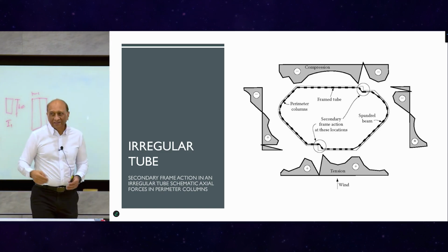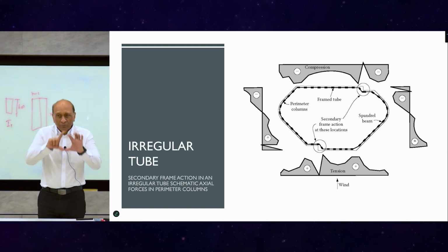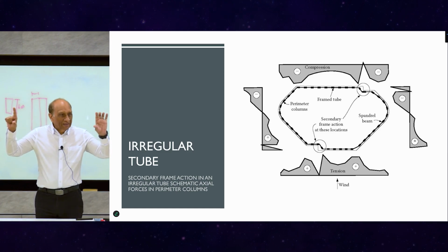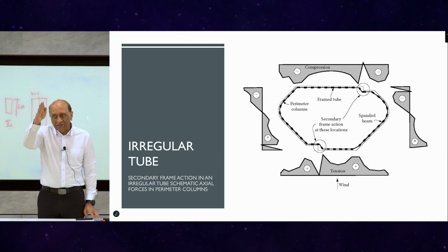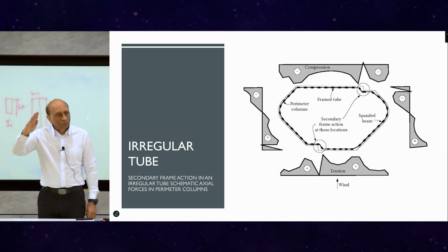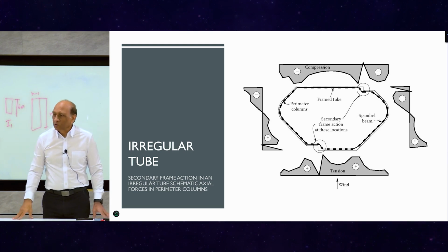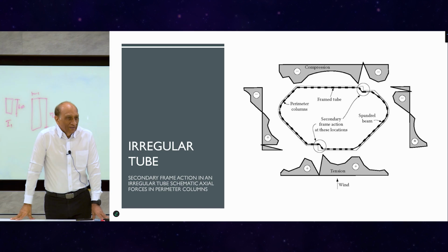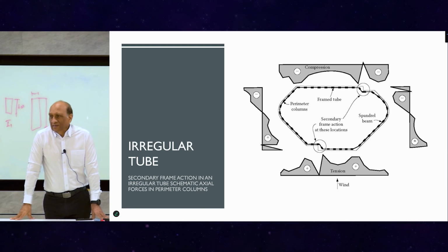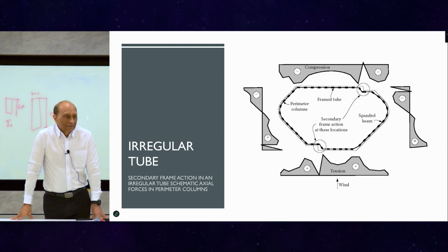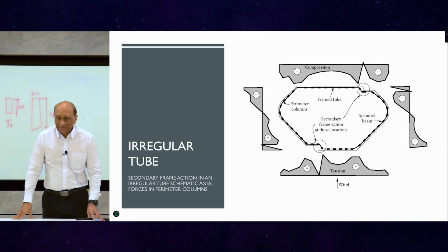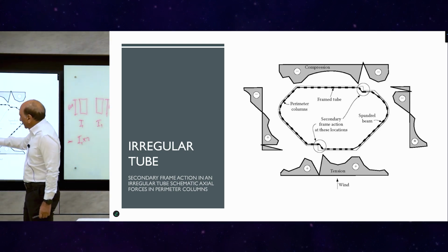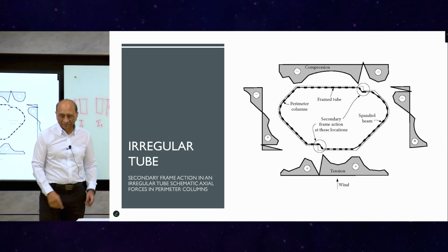Now, when we go to the next step, when we do the analysis, you will see that as soon as you put an outrigger in a building, you will have the same kind of issue with the moment and shear plots. Suddenly the very nice smooth moment plot and very nice smooth shear plot will be doing something like this close to the outrigger, because the stiffness changes rapidly. So you have large discontinuities and large stress concentrations close to the outriggers, because as soon as the stiffness changes, you get these discontinuities. So that's the problem in all these irregular tubes. Things like this obviously create serious problems.